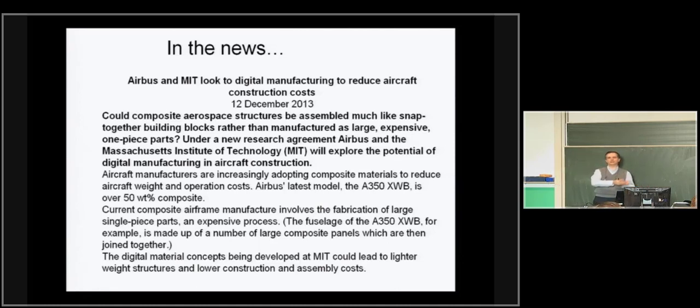If I make something, I need to connect it with something else, and the assembly process is quite expensive. In fact, roughly you can assume it takes about a minute per fastener to put something together. So if you have thousands of fasteners, there are thousands of minutes worth spent. You might argue, okay, I will do bonding, but if you do bonding, then your structure cannot be easily demonstrated to be damage tolerant.